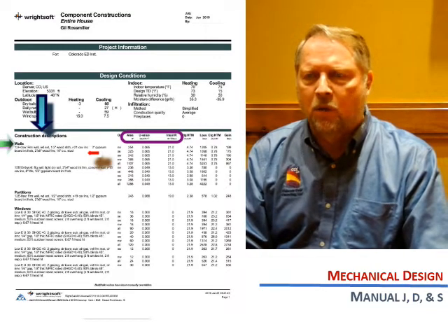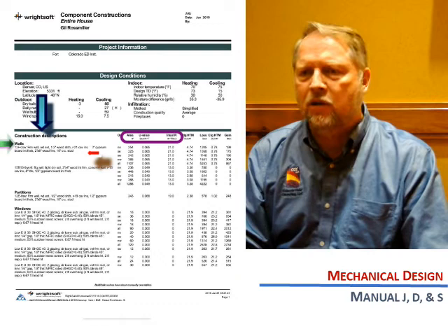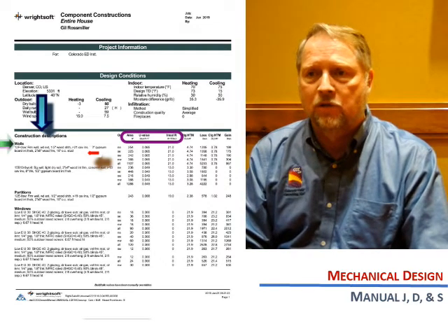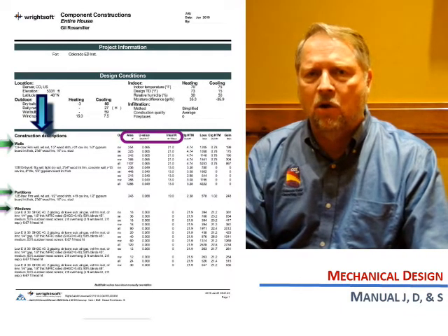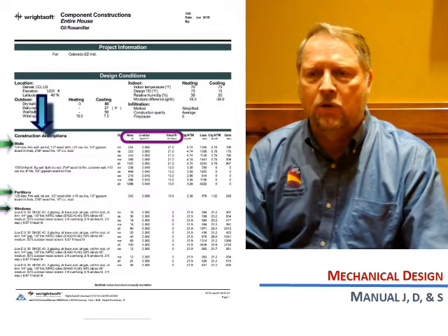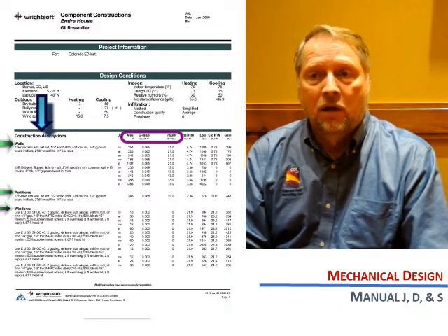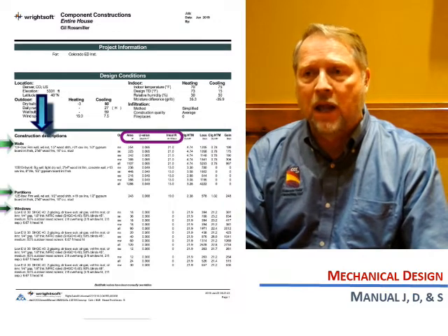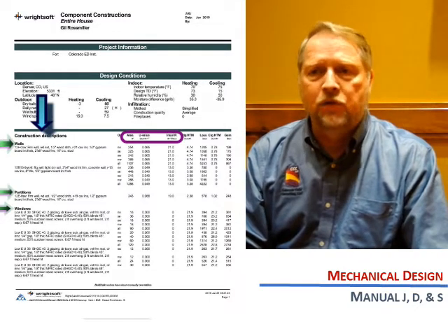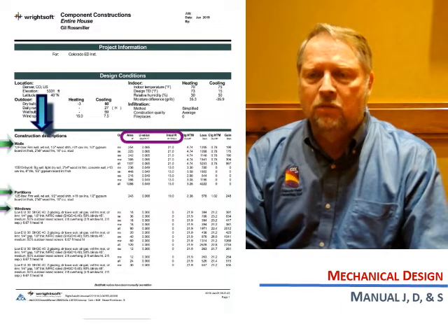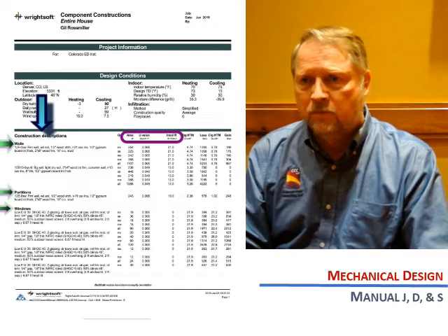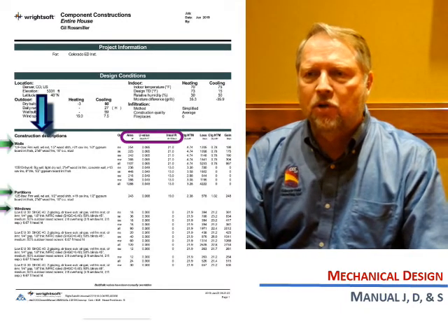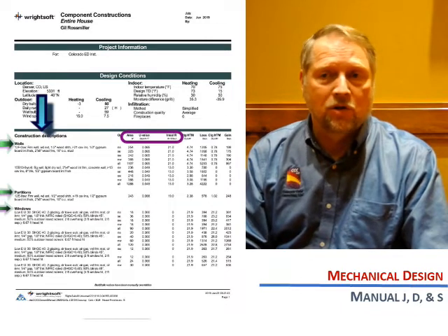Wall assemblies, your thermal envelope, their R values, their U factors, and the square footage of those areas. We should be certain we have all the types of assemblies that are in the house: below grade walls, above grade walls, slab on grade floors, floors over cantilevers over ambient air, and roof ceiling assemblies. All of these values should be very close and match the values listed on the plans and energy compliance documents. Remember, these are the values used to determine the size of the equipment to install. So these are all very important parameters that we need to make sure are there.